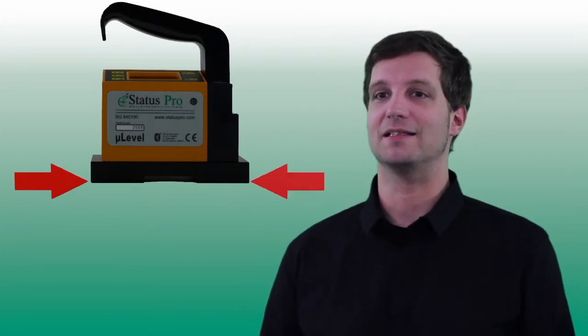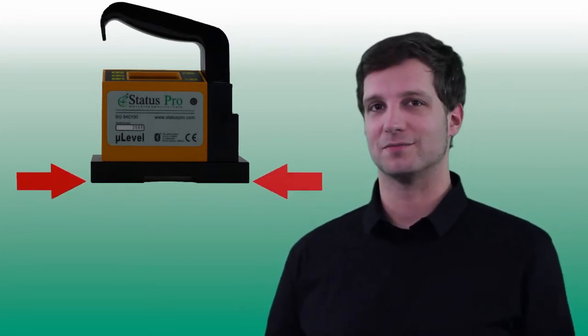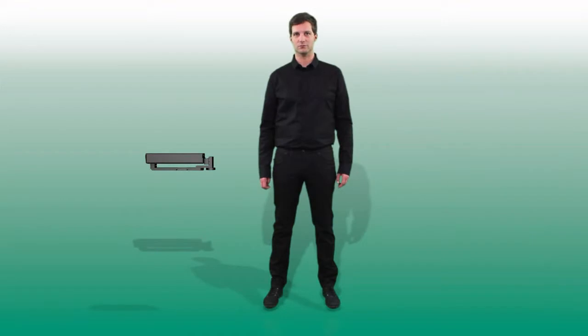Digital spirit levels, for example, have an excellent local accuracy. However, the basis is very small, typically less than 200 millimeters long. Nothing on this earth measures distance more precisely than an interferometer. However, using this property for the purpose of flatness measurement requires the introduction of additional optical elements like prisms and mirrors. These must be precisely aligned, and that is something which is done better under laboratory conditions.